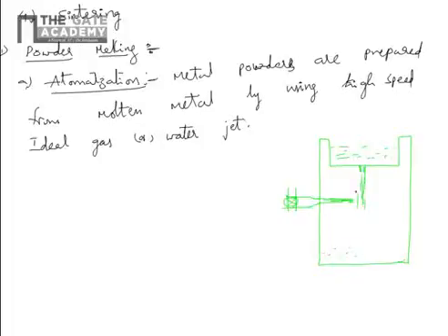You keep a hole in the tub holding the molten metal, so the molten metal falls down. At 90 degrees, use an inert gas jet or water jet and project it onto the stream, such that it creates fine minute metal powders, which are collected. This is one of the best methods to create metal powders for hard materials.